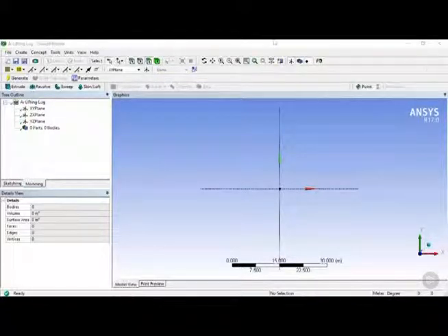Moving on, we have the Rotations mode toolbar. So here we can use the Rotate view. We have a Pan view over here. Here we have Zoom, Box Zoom, Zoom to Fit, Toggle Magnifier Window, etc. Here we have to set an ISO view. We also have a section plane, so you can create a new section plane using this tool right here.